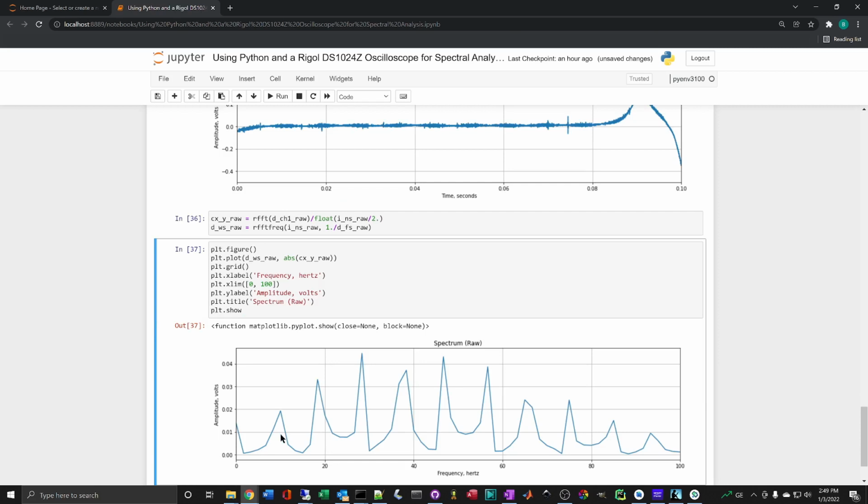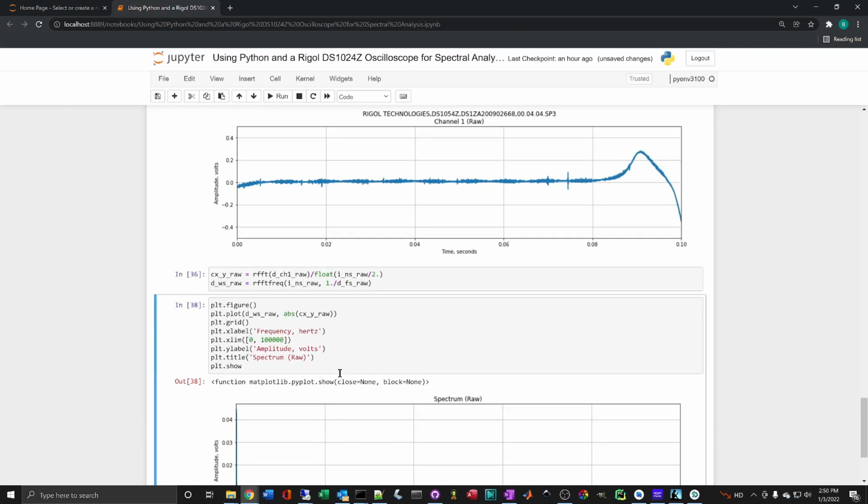And again, you might be a little disappointed in this if you spent all that time and you were looking for low resolution data. I won't go into it here too much, but what you get out of more samples with the same time interval is you get more samples off to the right. You don't get more samples in this low frequency area. So this is what we would expect. If you want to see the real power of a high sample rate, take that X limit, that frequency axis, way out.